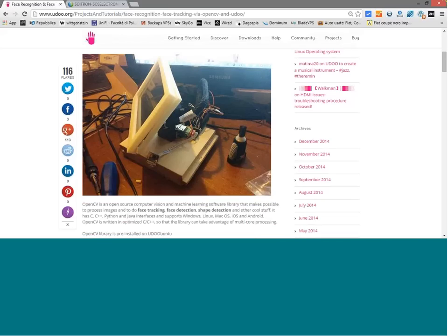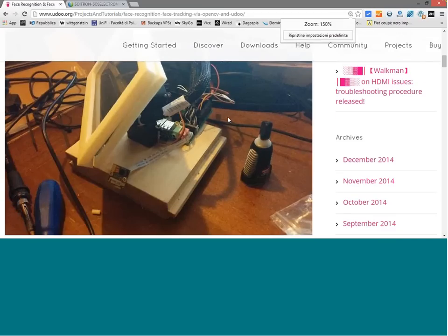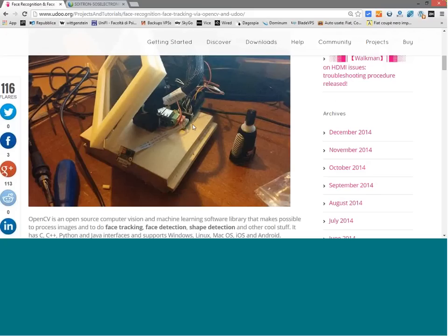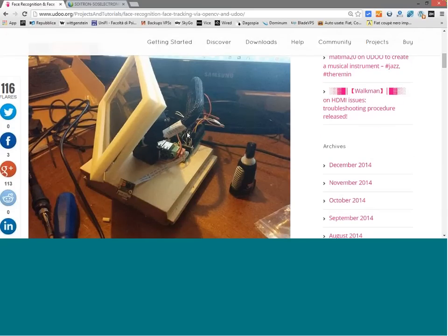So you see we connected our motors via these pins to UDOO, to the Arduino side. Then we connected our LCD screen to the LVDS port. These screens are designed to be just plug and play with UDOO, so you are just meant to attach them and they will work. Then we attach the CSI camera module to the camera connector on the UDOO board.